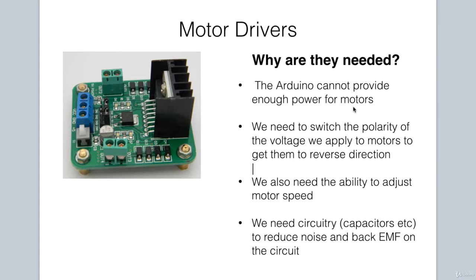What this means is that we typically have to provide an external additional power supply for our motors to operate, and we cannot connect the Arduino directly to our motors. A motor driver allows us to connect an external power source to supply current and voltage for our motors, and then regulates the current that is provided to the circuit.